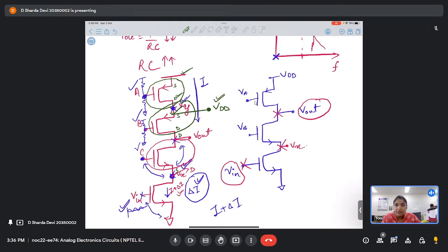So basically, the advantage that we are getting is due to these floating nodes which are present, which don't have any fixed value. They change according to the situation. That's why we are able to do this. The moment we connect a DC voltage to them and they become a DC node, then no matter what you do, you can never change its potential. It will be pinned to that particular point.